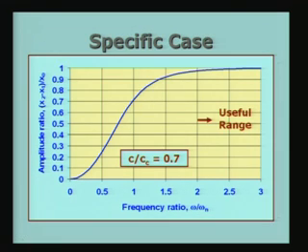So, the thing we notice is that for measuring the amplitude of the vibration, the useful range of the instrument is such that we must have the input frequency greater than about 2 times the natural frequency of the system. So, you can immediately see that if we are going to measure the amplitude of vibration of a system varying at a fairly low frequency, then omega n must be even lower than that. For example, if I have a frequency of 1 hertz, this factor 2 means that the natural frequency must be even less than that, half a hertz, half of the impressed frequency. Therefore, your natural frequency must be chosen even smaller than that. We will discuss when we take up an example, it will become clear to you what we are talking about.